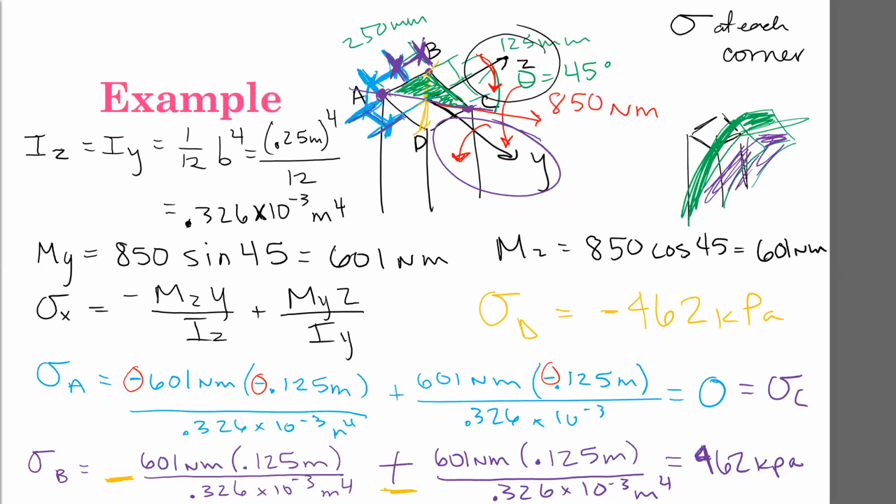And then this other side, this triangle, will all be in compression. Good observation. So that's the neutral axis for the whole thing? Yes, that's the neutral axis. It goes across? Yes, the neutral axis goes all the way across the member. No, longitudinal.